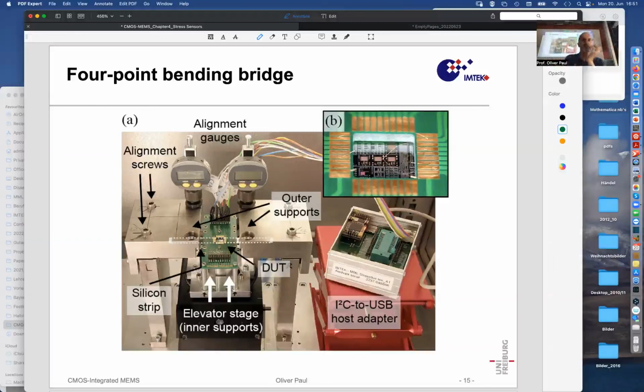And so for the mounting, the PCB and the stripe are somehow intricately pressed against each other by these screws. There is a little structure under the stripe that holds the stripe, and you can mount it, and then you loosen those screws and somehow elevate the green part a bit away. While this is being done, the bond wires deform a bit, but thanks to correct bonding, this is feasible. And then you have a freely moving silicon stripe underneath.